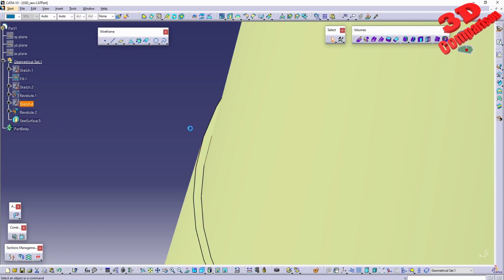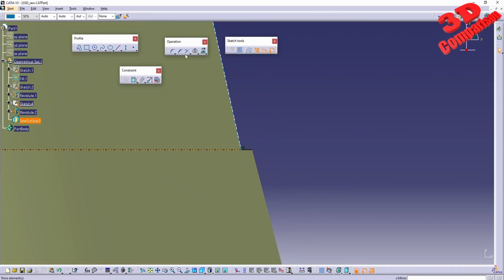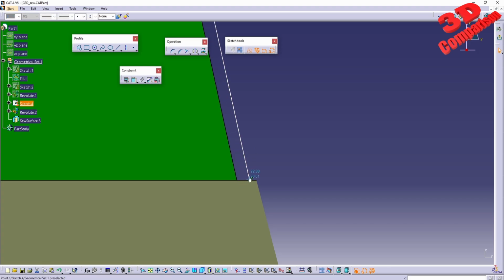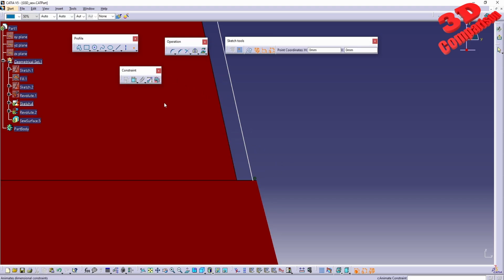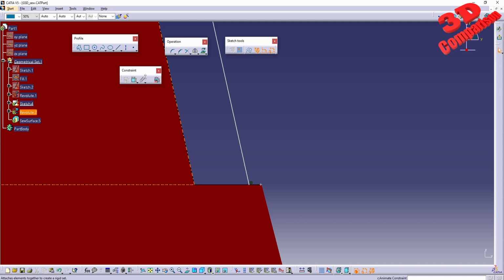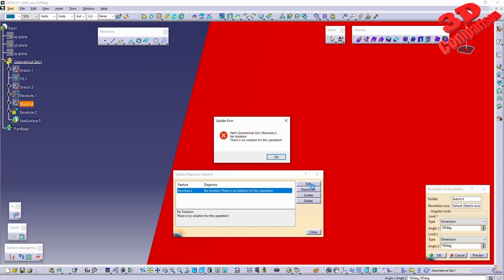If I will go over here onto that sketch, and if I will add a constraint between that section and over here, all the way to the top, so all the way to the side, let's see, something like that. I will just try to add a point over here on the end of that. It's not perfectly aligned, but I'm curious what is that distance over here. So we see that this is currently set to 0.042. Therefore, keep that in mind that if it's within that desired tolerance, it will work.